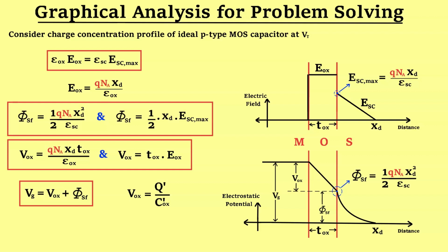This is not a new formula. We have used it in the previous lecture. It should be clear to you all that a parallel plate capacitor has two plates on which charge is deposited when a potential drop is applied across the plates. The charge on the two plates is equal in magnitude but opposite in sign. So, a little confusion may arise about what this charge is in this equation. In standard books, it is completely dependent upon the author whether he wants to consider the charge on the metallic plate or the charge on the semiconductor oxide interface. But here in my lectures, I will always consider the charge on the metal oxide interface.